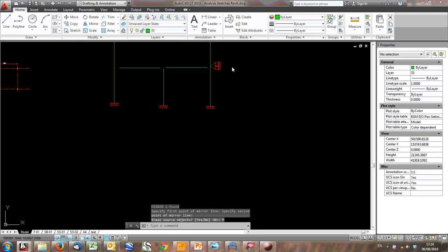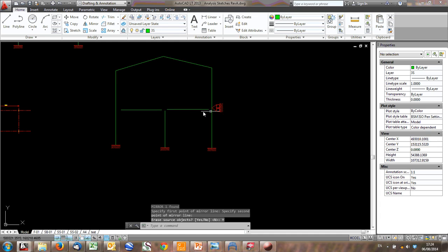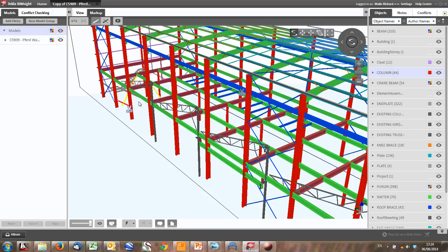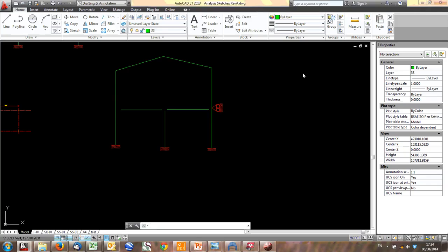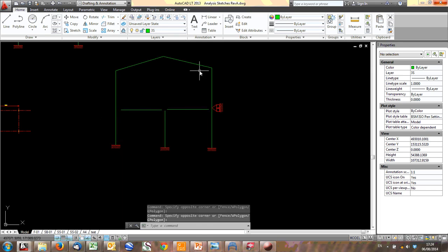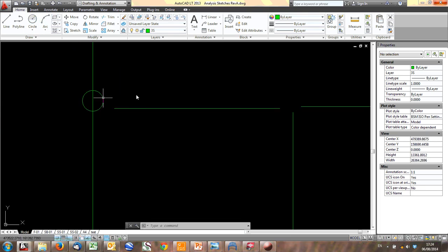You add a prop, and this is the force that you then take all the way down to the bracing that is here, that I've just drawn in, and here. And in that way you can stabilize the structure. And you can use a diaphragm action, a diaphragm of the floor here, to stabilize this entire structure. And especially, I mean, if this was, let's say, a concrete structure here with a steel structure on top, it'd be the exact same story. What you might just add in then is a pin here, and a pin here.